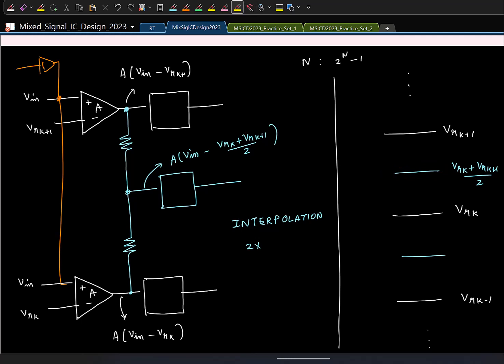Yeah, that is actually one thing. Resistors need not, but it turns out resistors can be matched with decent accuracy. One simple thing is, here it requires that I have to use a preamplifier. It can so happen that for my comparator, I don't even require a preamplifier. I can just tap the latch directly. But for this trick to work, I definitely have to have a preamplifier, right?